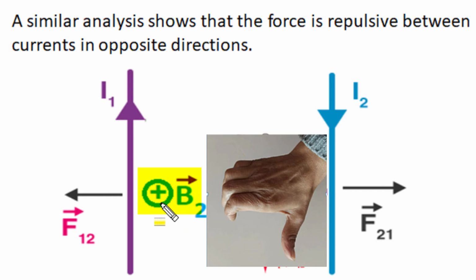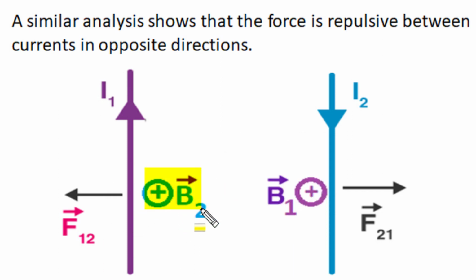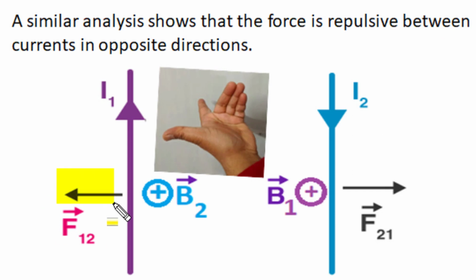as shown by crosshair. And when a current carrying conductor is placed in a magnetic field, it has Lorentz force, and for a 90-degree angle between current and magnetic field, the force magnitude is maximum, and the direction of force is given by Fleming's left hand rule, which is repulsive as shown by the thumb of this left hand. When the forefinger is directed along the direction of magnetic field and the middle finger indicates the current, then the thumb indicates the magnetic force on the current carrying conductor placed in the magnetic field,